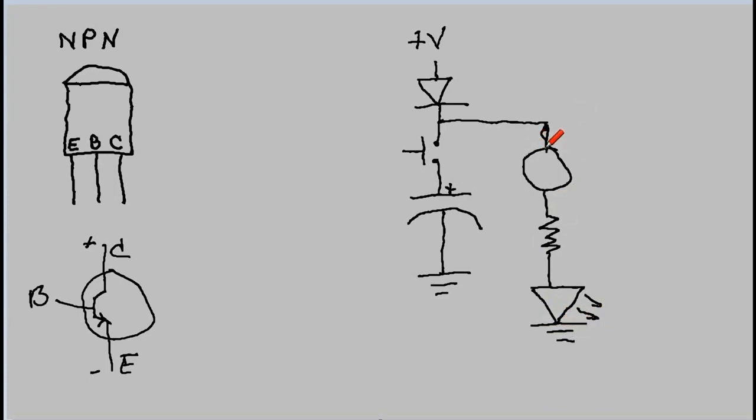Okay, now this goes down here, over, down, over, down. We've got our little arrow, because that's where the emitter is. This is plus volts, this is ground, as we've learned from an earlier lesson. Now we come off of here with another resistor to our base. So basically what you're looking at here is plus volts. I know it looks like a 1. So this is our little circuit using our NPN.